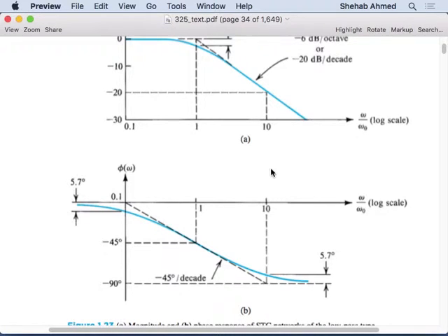If there is a phase shift between the input sample and the output sample of 90 degrees, that's what? 90 degrees is one fourth of 360, right? So my sampling frequency is 20 kilohertz, and 1 over 20 kilohertz is the time between samples. Because of my amplifier, there was a delay in the signal, so the output signal is delayed from the input by 90 degrees. 90 degrees is 1/4 of my full period.